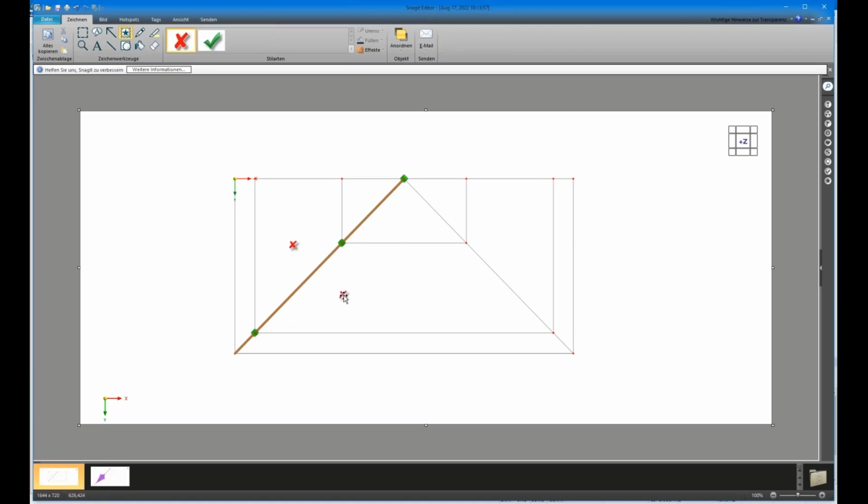And how do we get it? We get it by taking 50% of the span length. Now we can measure our tributary length by measuring this distance. Depending on the projection plane and so on, but when we are in the projected area, we can use this value directly. And the tributary area in this case is exactly here, this purple highlighted area.